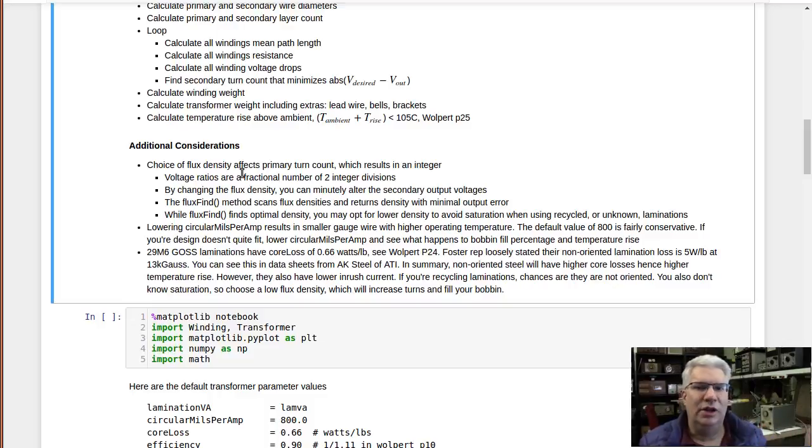When I first started working on this, I thought I could just put all these equations into a nonlinear solver and have Python's code figure out everything. But it turns out that being an iterative solver, having to force your turns count to be integers makes it complicated, because the stepping algorithm in the nonlinear solver will get confused by that discontinuity, and chances are it won't converge.